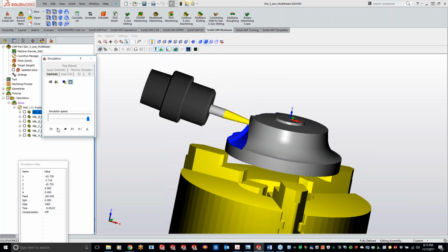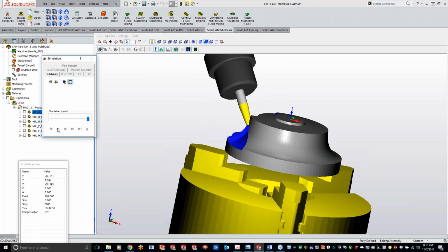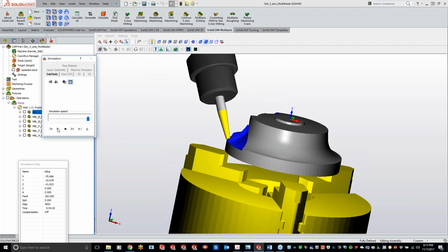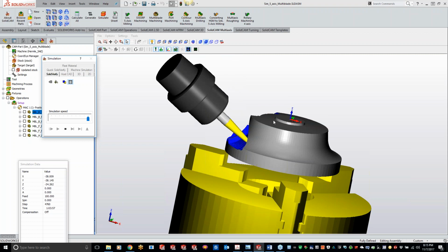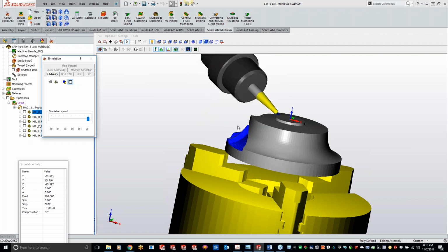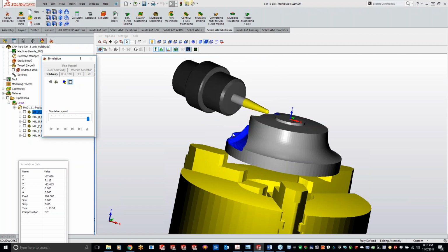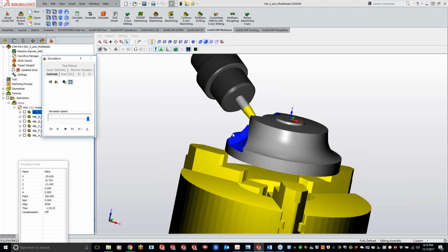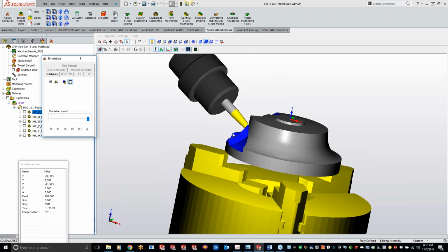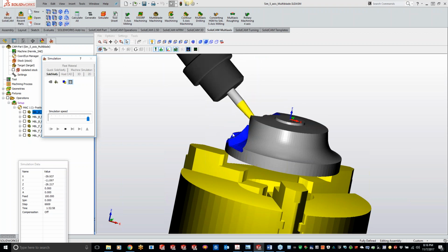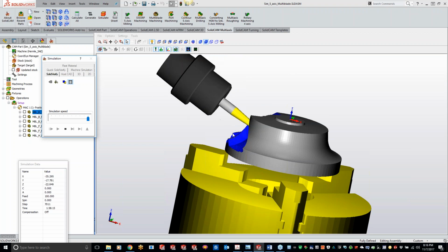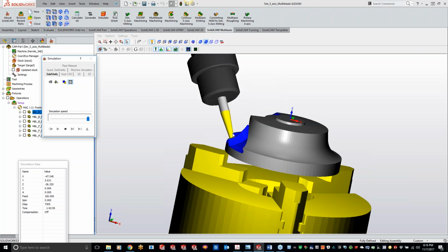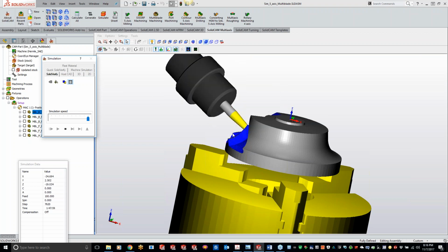What we could do is set up, if you didn't want to use the roughing strategy inside Impeller, what you guys could do is set up a secondary coordinate system, tilt it over so it's at an angle, and we could also use 3D iMachine to rough it out. But it's not going to get as deep and as good in there as what the Impeller roughing strategy is going to do for you guys. Just because this toolpath is specifically made just for Impellers.